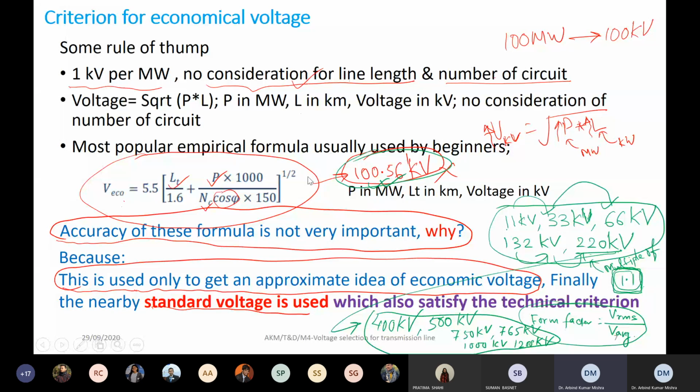One thing you might remember from the course on electrical machine design: if, for example, you design a transformer, every time you change the primary and secondary voltage you need a special design. But if the primary and secondary voltages are fixed, varying only over a narrow range of power, then the transformer is ready made.